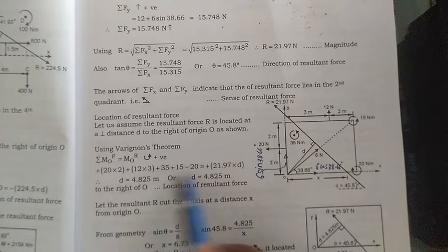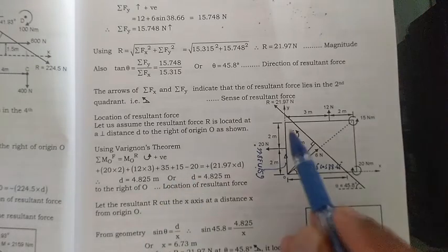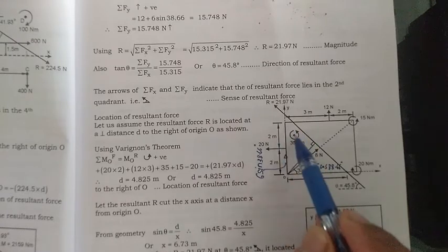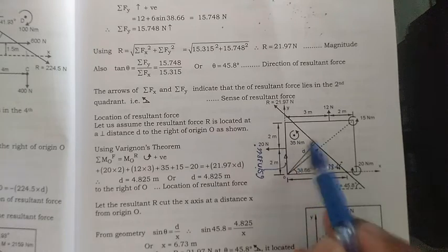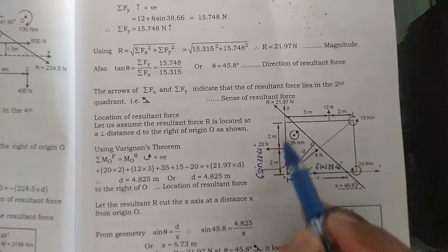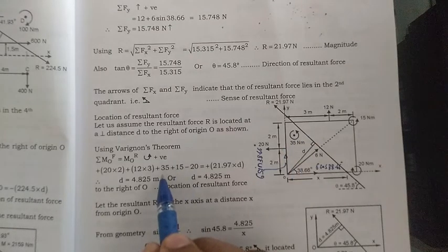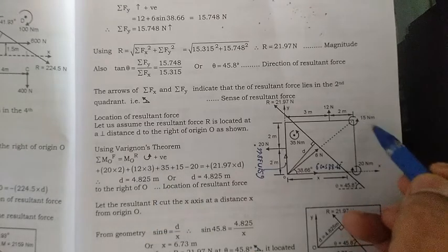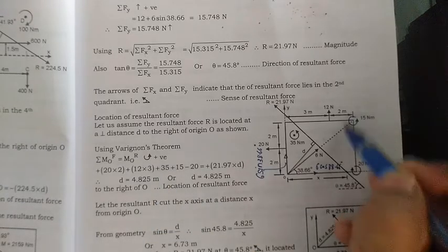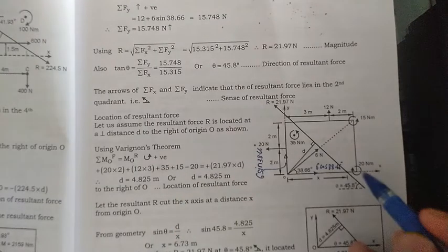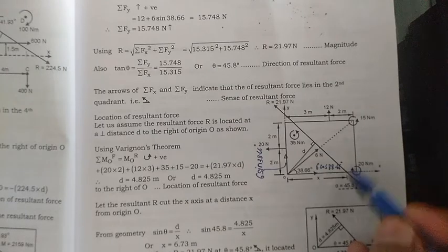What about the next one? The next three are very important. The couple is shown here. Now see the tendency of this couple to turn about this point in the anticlockwise direction. Don't multiply by any distance with this couple, because that distance is already included in the couple value. Here we have 35 Newton meter. The tendency to turn about this point is anticlockwise, so consider the positive sign. Next, a 15 Newton meter couple with us. Its tendency also is to turn about this point in the anticlockwise direction, so give the plus sign. Next, the 20 Newton meter couple turns about this point in which direction? In the clockwise direction. Give the minus sign for this one.